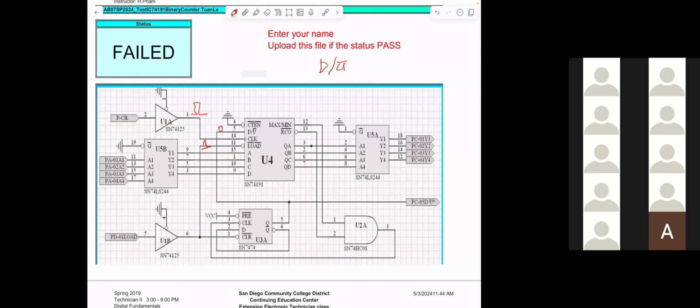If you understand that, then when they're not counting up, you know how to troubleshoot it. When you troubleshoot, you check to make sure pin 14 you get a clock, pin 5 you get a 0, and pin 11 must be logic 1. Okay, any question, anything up to that?